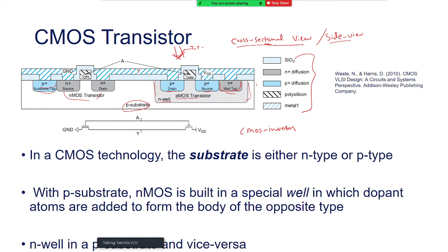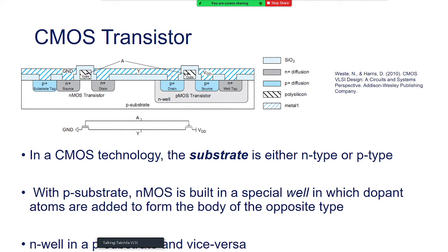Okay. Now once that is done, what I see here between source and the drain in NMOS, I have this gate, polysilicon obviously, and on top of that gate I have SiO2. This is SiO2 basically. That is oxide. It's just an insulator. What does an insulator do? It avoids the conduction and shorting of one area to another area. So it's just there for the isolation.